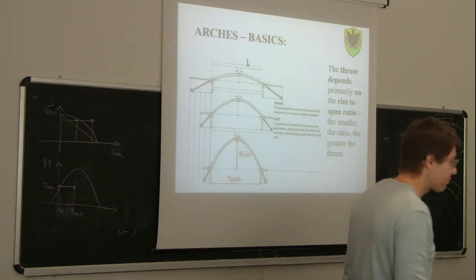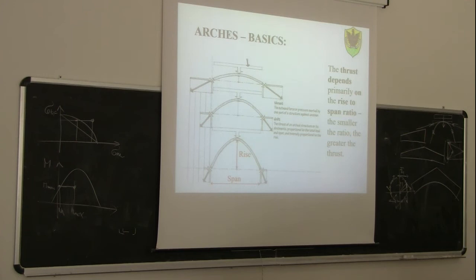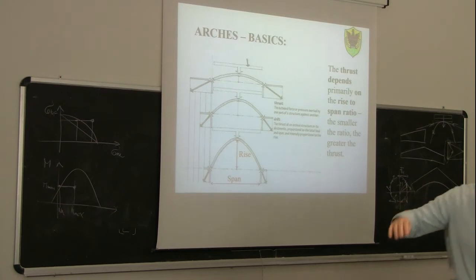This was a bridge with a very small rise, if you remember. The old bridge had quite a big rise. The new one was very flat, very small rise. And of course, the restraint reactions were very big. In fact, they had to build a significant foundation underneath, like I was told, like a building of 5 stories, just to have underneath the ground to keep this reaction.